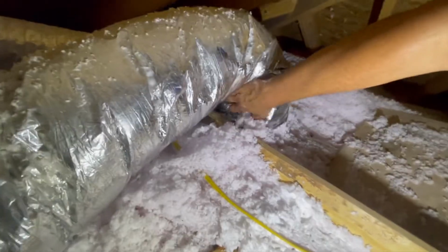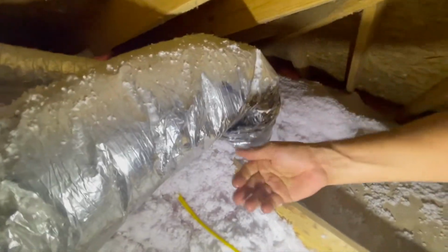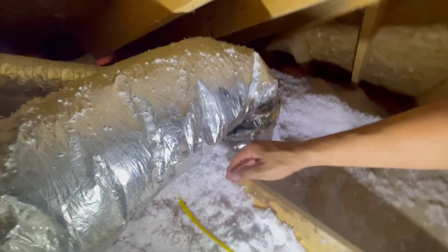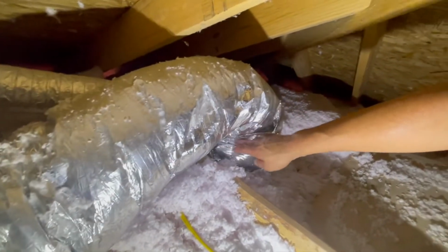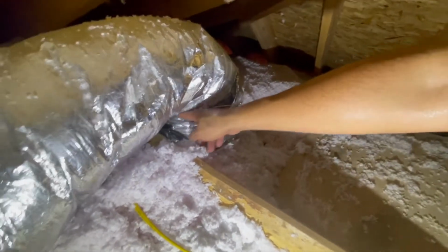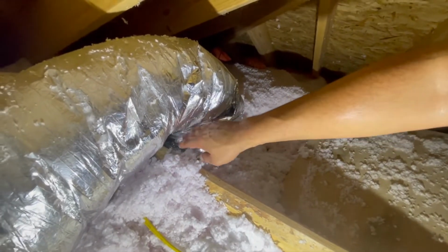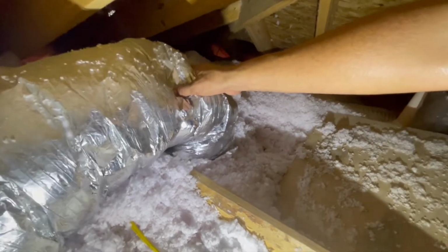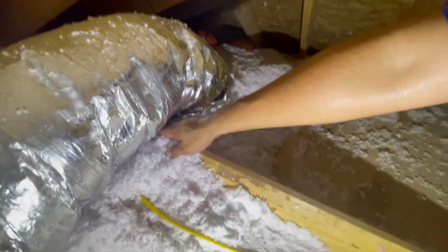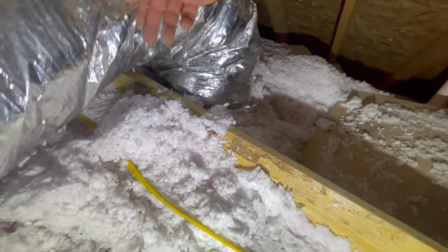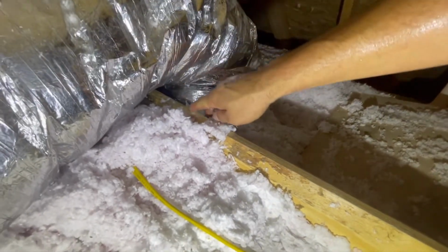This duct is physically wet from sitting in insulation. Also, this turn in the flexible duct is causing it to crimp, and so it gets very turbulent and slows the airflow down. And then right here where it's making contact with that wood, oh, look at that wood. Let's do a close-up right there. You're going to get a lot of conduction. That wood's wet to the touch.